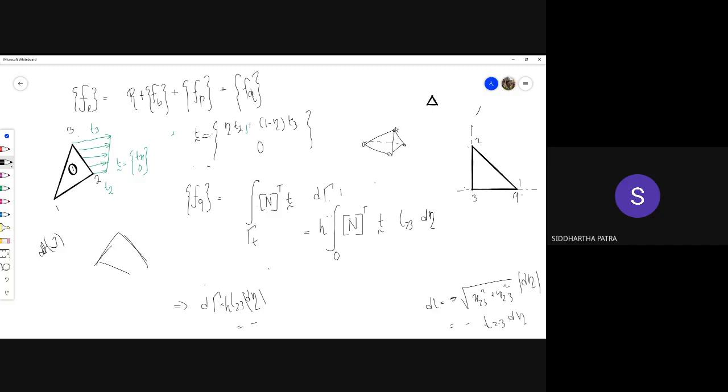Somehow this node is trying to penetrate this surface and going to the opposite side. That's what is flipping. And in order for an element to flip, there has to be a situation where the volume becomes zero. Okay, physically the volume can never be zero. And therefore that becomes a warning for the finite element software that there is some error going on, there is some problem going on with the solution, and that the solver determines through the change in sign of the Jacobian.